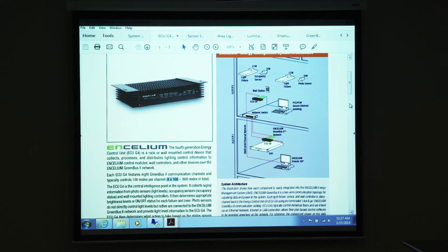Which would come to the backup. We run a backup. I'm not sure exactly how many ECUs we have. I want to say there's one per floor, but I think it's one every other floor. I think one takes care of every 2 floors. Might be right. I'm pretty sure that's the way it is. So there should be 3 ECUs. I believe so. So if we back that up, let's say we have an ECU fail, we get another one sent, we should be able to take our backup and plug in and restore. Yep.